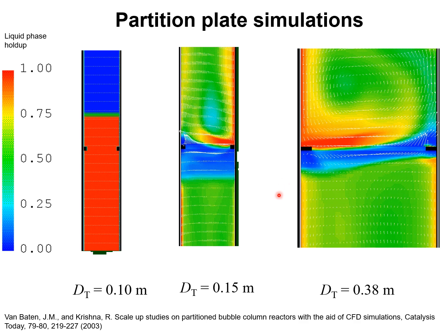So reduction of back mixing is just one positive aspect of soaker vessels with internals, but it appears certainly qualitatively based on the CFD simulations that there is a real danger that there will be dead zones and high residence times of liquid in certain portions of the column.